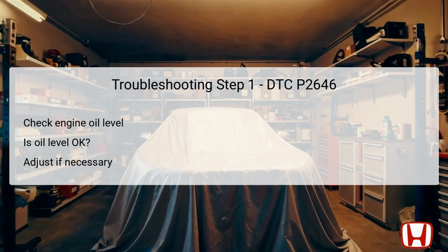The first step in troubleshooting DTC P2646 involves checking the engine oil level, as insufficient oil can lead to low pressure and trigger the DTC. The oil level should be checked using the dipstick to ensure it falls within the manufacturer's specifications. If the oil level is found to be low, it must be filled to the appropriate level before proceeding to